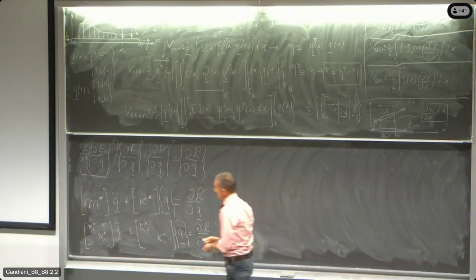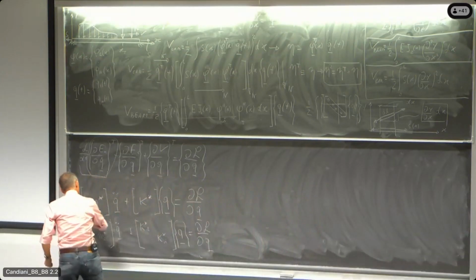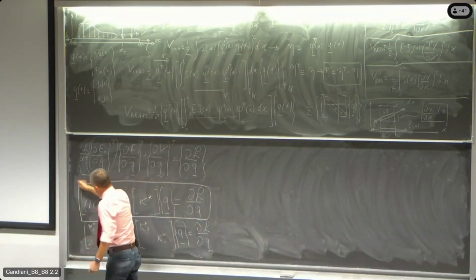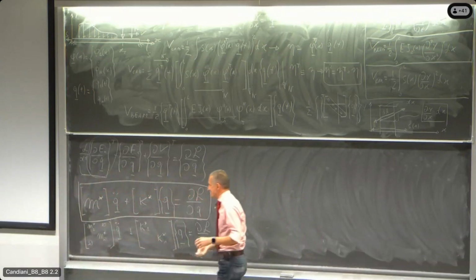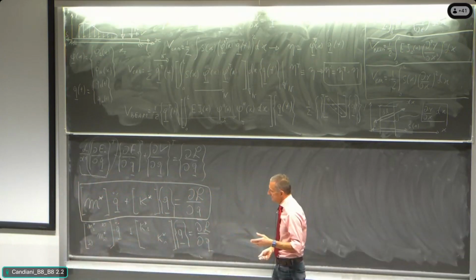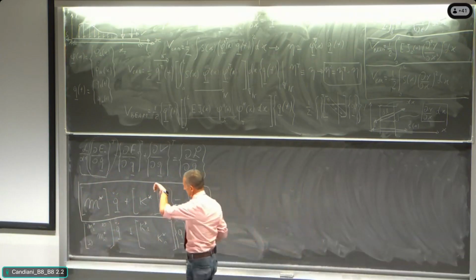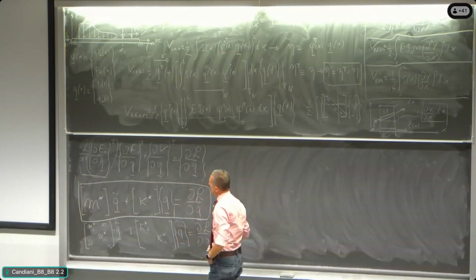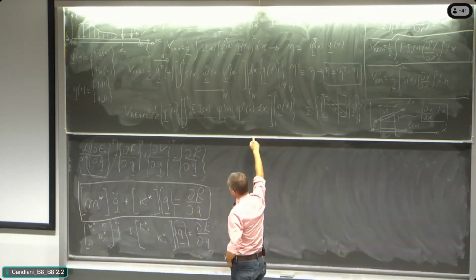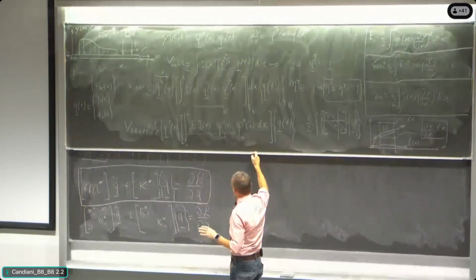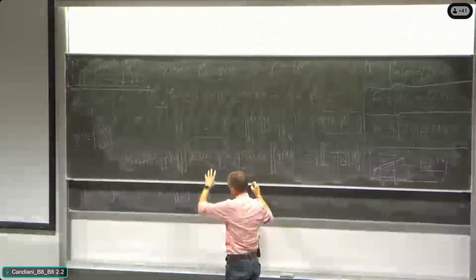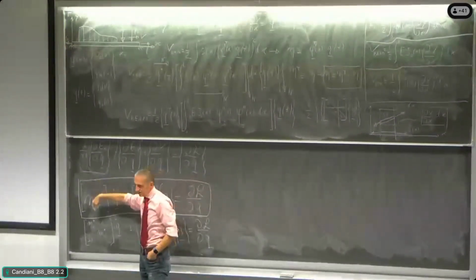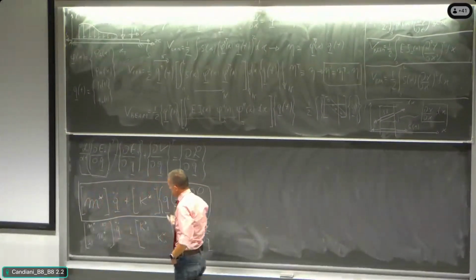All right, and so the procedure is we solve the free motion problem. We calculate the modal shapes, the eigenfunctions phi. If we have to do that calculation, it happens very seldom. We are working with these quantities. We are calculating the diagonal components of the mass matrix and of the stiffness matrix.